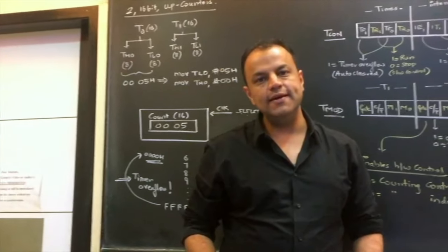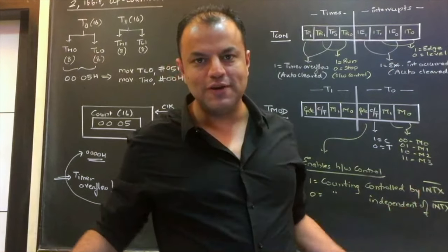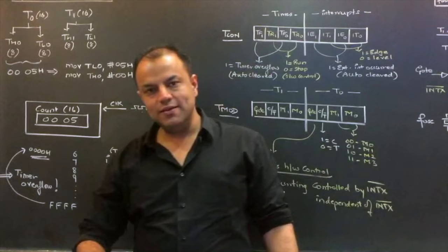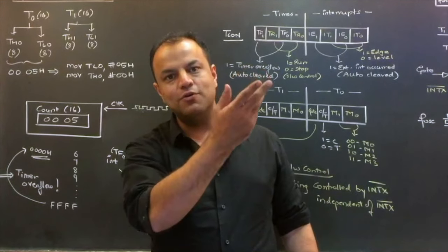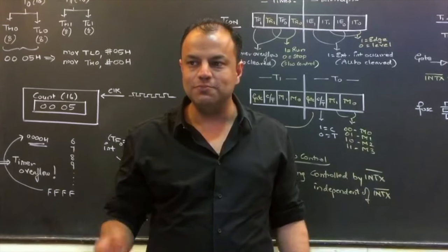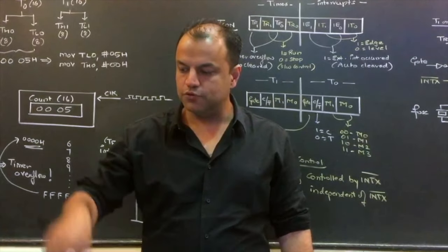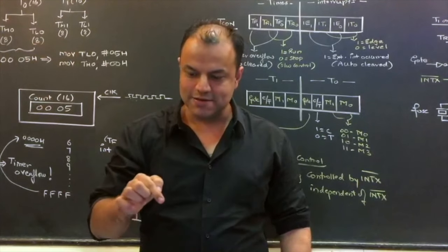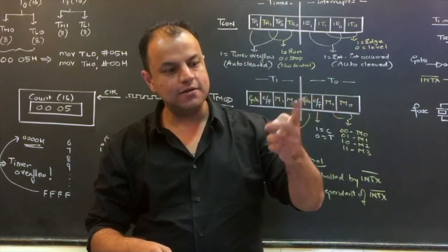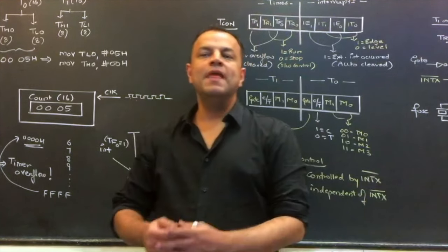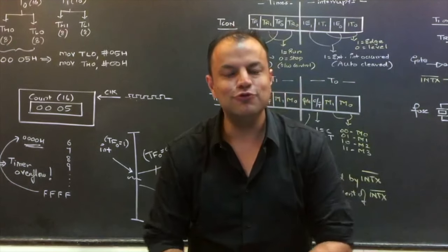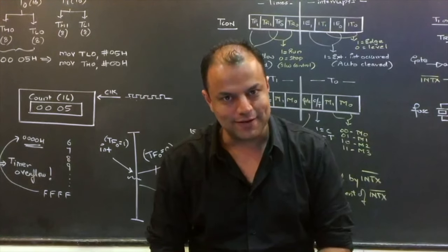So students say, then what is the purpose of this flag? Instead, when the timer had overflown, it should have sent the interrupt and we would have gone to the ISR. That would have been so simple. Now, the timer overflows, makes the flag 1, sends the interrupt. We go to the ISR, the flag automatically becomes 0. So why do you need this flag? These flags are used to store the pending status of interrupts.